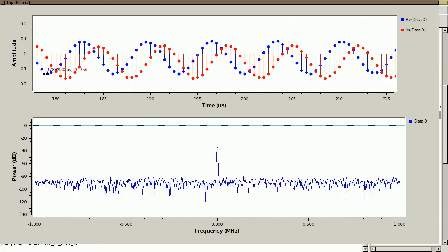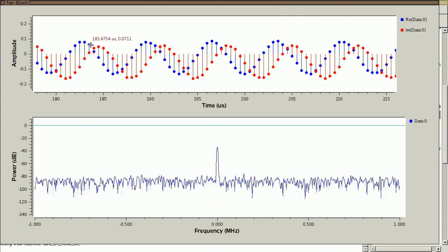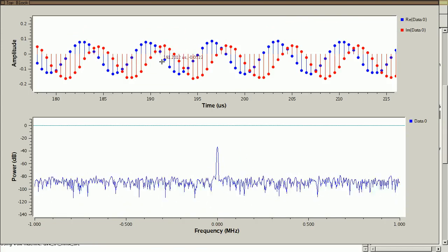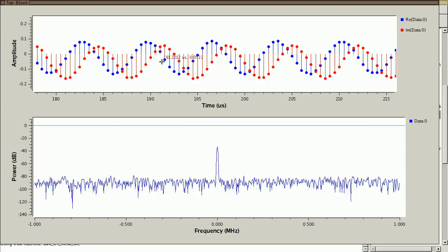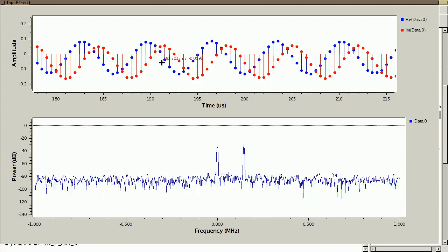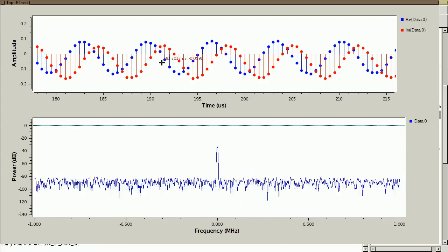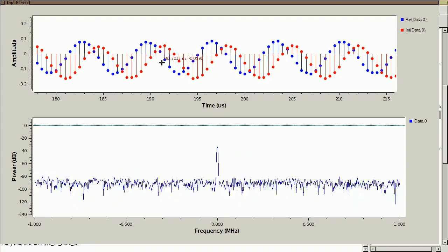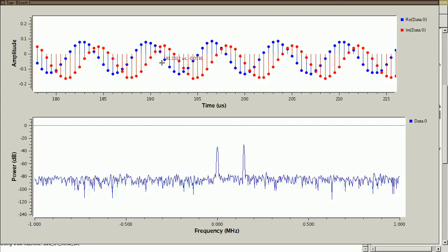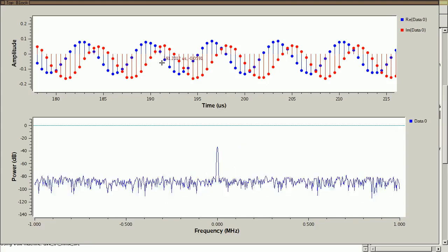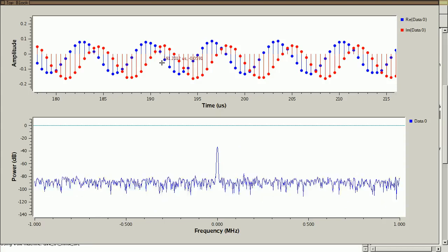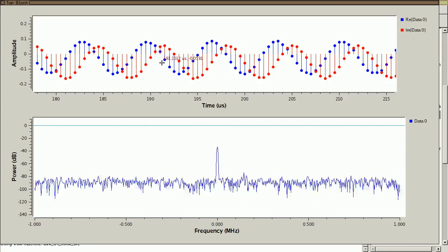Notice that these are only extending about 0.1. The amplitude is fairly small if you think of maximum amplitude being between negative 1 and positive 1. That's the scale that we expect, because when the Osmocom source receives information from the HackRF, it takes these 8-bit values and then scales them and assigns them floating point values that are between negative 1 and 1.